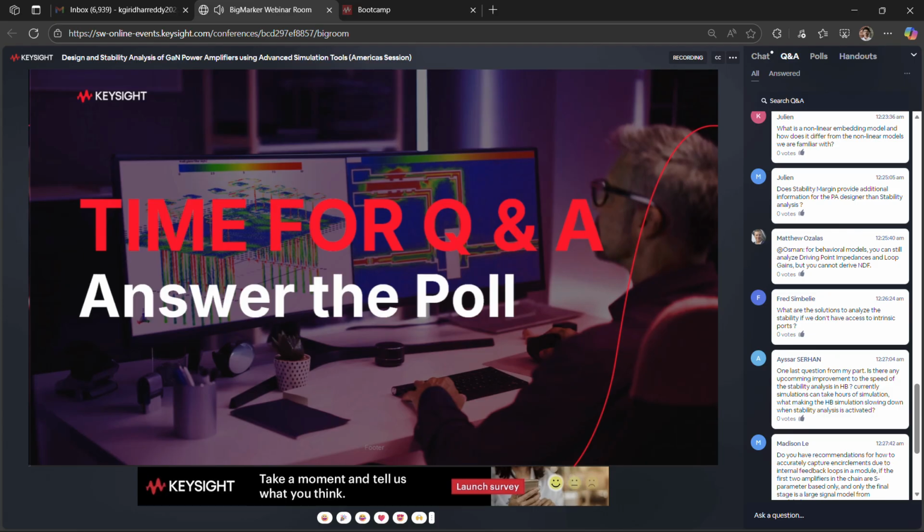Now for the Monolithics devices, that's not required because the probes are already built in. So you don't have to worry about it if you're using Qorvo Monolithics devices. That already has it. But the other thing that you can do to speed up your stability analysis is you can automate the results part of it, the data collection part of it. So you can create a data display page in an automated way that figures out how many devices you have and how many probes you have and automatically runs the equations for you and does some type of stability analysis.